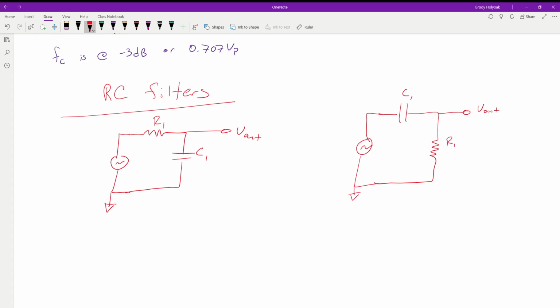In this instance, we're going to apply some values and solve it. One thing to think about is what is happening in the circuit as we sweep our frequency from 0 up to 2 meg, for example, or 20 meg, or whatever we want to do. What's going to happen with each of these parameters? Remember, our X of C goes down when our frequency goes up, and that's true in both situations.